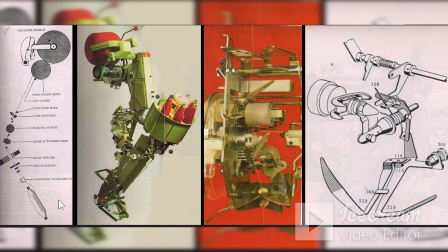Please note that you are not sensing at the ring frame bobbin to know whether it is exhausted or not. But when yarn is absent in the gate filler, it is considered that the ring frame bobbin is exhausted. But it may not be the case always.